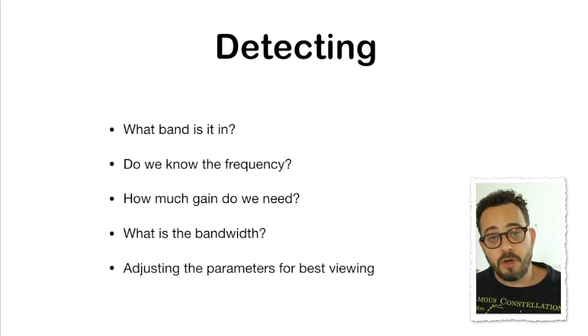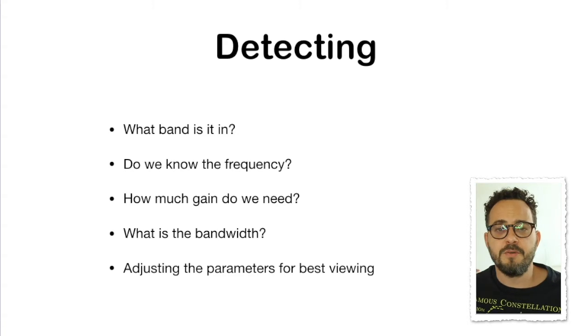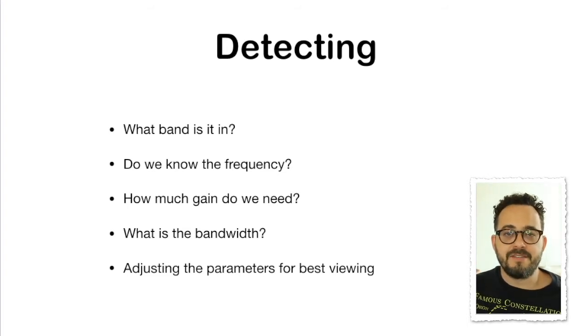So if you go too low, you won't see anything, even though it's there. If you go too high, you might distort your signal, so you might need to work a little bit on your own values to find the place where it's just right for you, where you get a decent reading, but still not distorting the signal. So now you might notice that I've set up an automatic transmission here, which is repeating itself, and we can see it in time and in frequency domains.